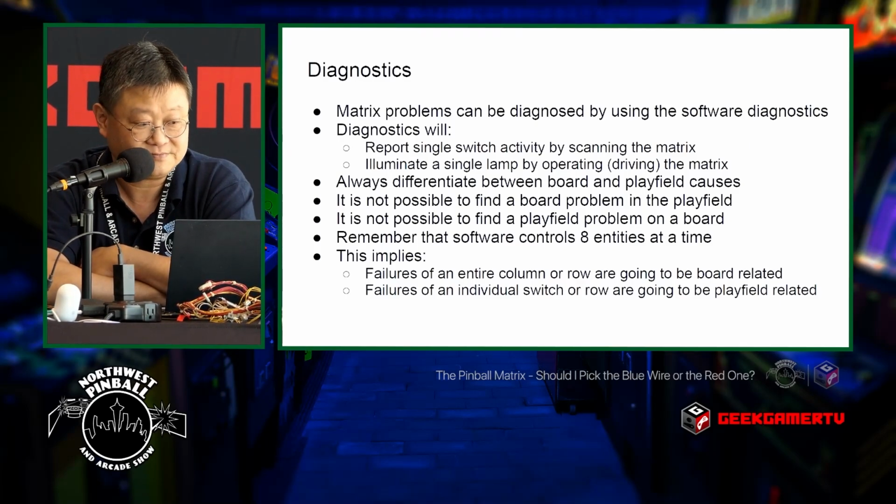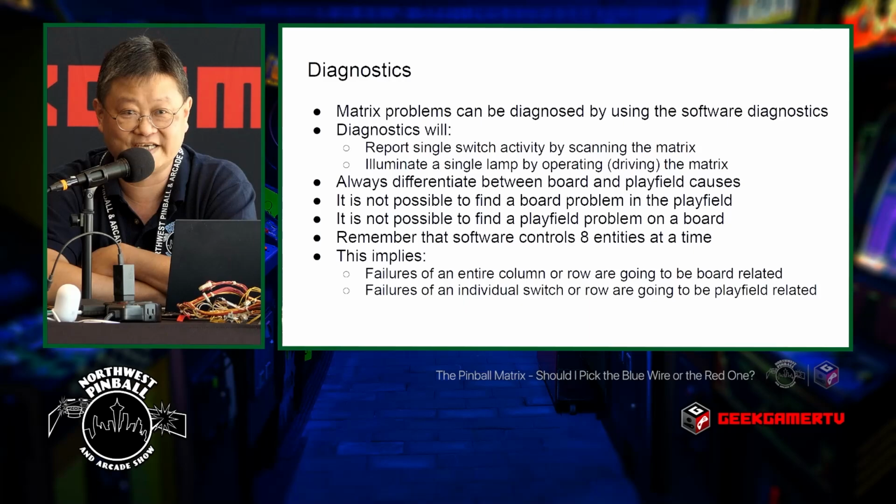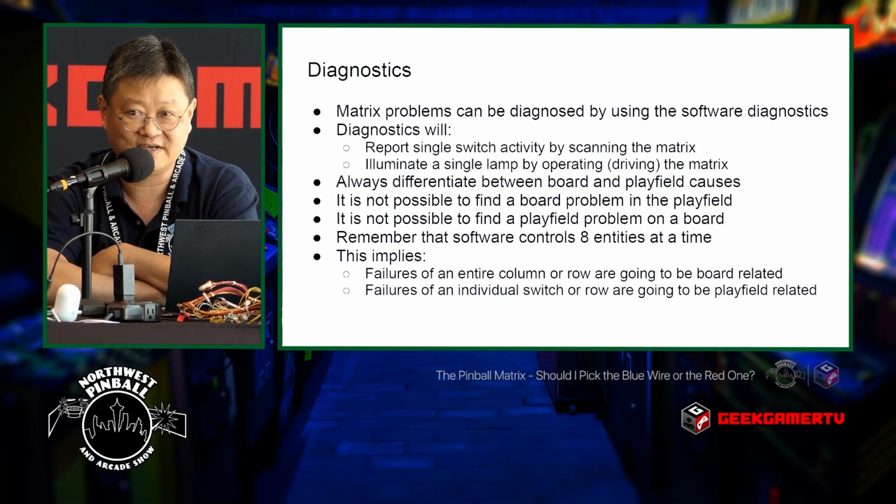Diagnostics. So matrix problems can be diagnosed using the software diagnostics. Not enough people use their game diagnostics. They say, this switch doesn't work. Well, have you tried testing it? And often, when you run the diagnostics, a byproduct of what the software reports will give you an idea of where the problem may be. Diagnostics will report single switch by scanning the matrix. Again, as it scans it all, it shows what the 8x8 shows. Same with single lamp.